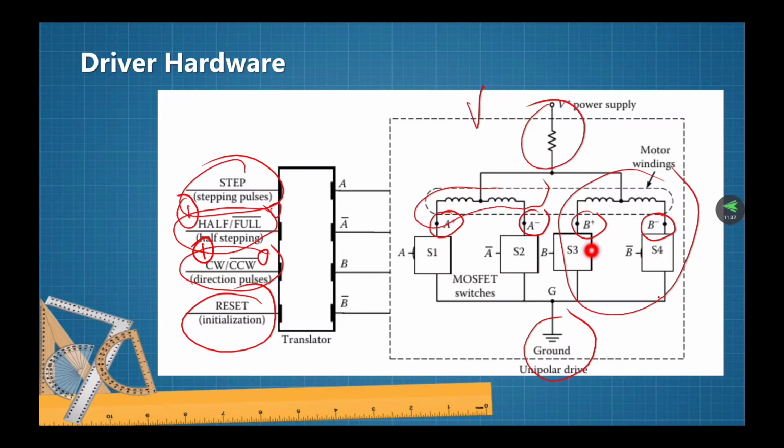The drive circuit for the phase winding has switching transistors to actuate the phase on-off, reverse in the unifilar case, on-off in the bifilar case, and the power amplifier for the winding. And then the driver needs a DC power supply to power the amplifier and logic circuitry.